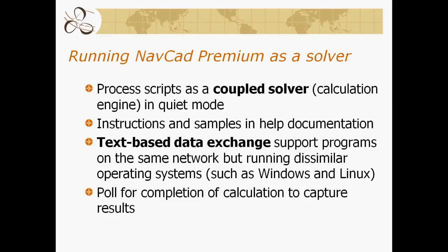One thing that we've done with the interface is we use a text-based data exchange. And the reason for doing this is it allows us to run NavCad, which is a Windows program, on dissimilar operating systems. For example, you could have an executive program on Linux, so long as it is on the same network, to run NavCad on a different Windows computer as a coupled solver and then return the data back to the Linux executive.